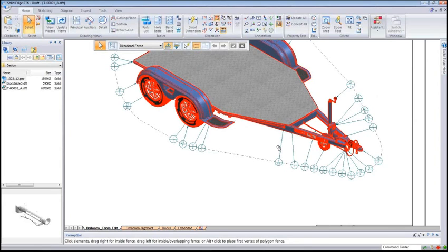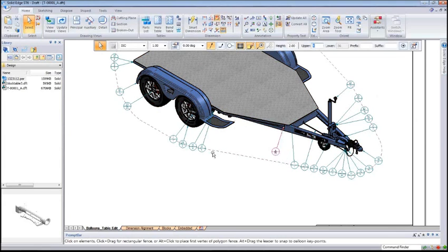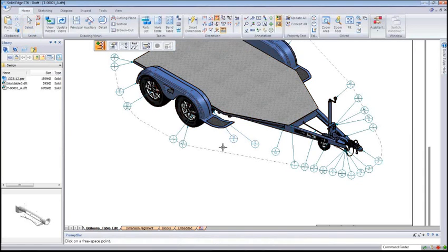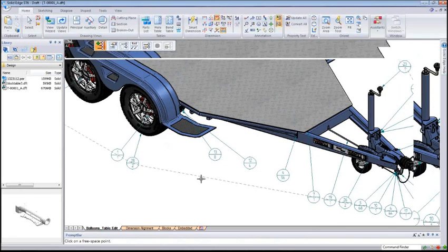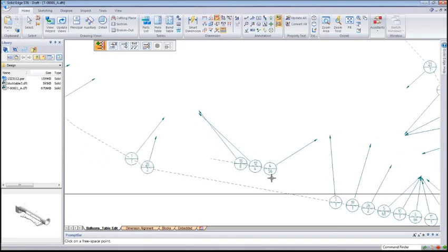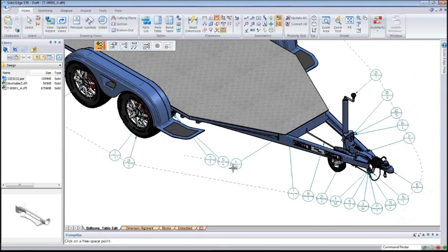I could also do things like, oh goodness, I can move my balloons off of this and maybe grab up a series of these balloons and maybe do things like annotation alignment shape. And I can say, you know what, I'd like to draw a line that goes from here. Notice as I move over it, they start attaching to this line. So now you can add in multiple alignments, which is darn cool.